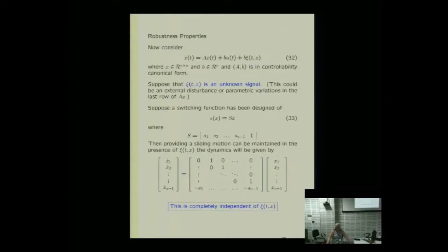They are quite different. The one is an analysis tool, which is seeking to say, how do we stay in the sliding mode, and which is dealing with the top part of those dynamics, the dynamics where the control doesn't act. That's where it is important. To the actual control, which is forcing S and S dot to have opposite sign. And clearly, if S and S dot have opposite sign, you cannot have S dot as 0, because it's strictly less than.